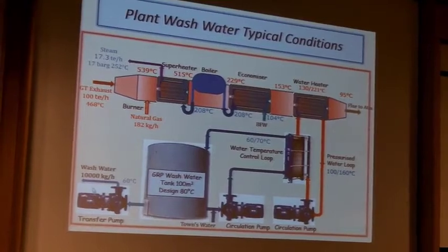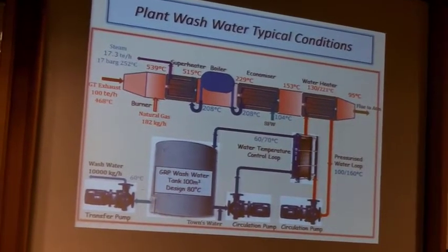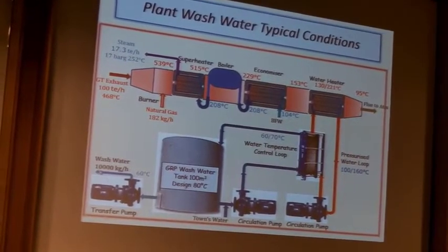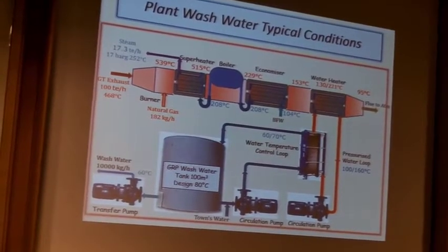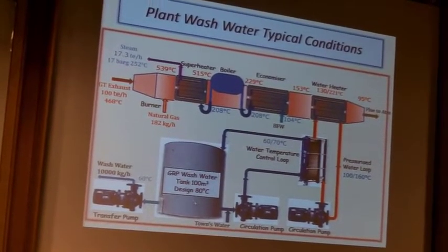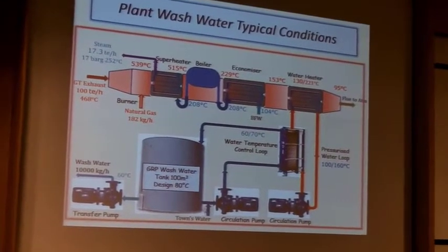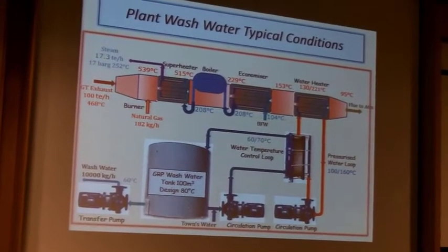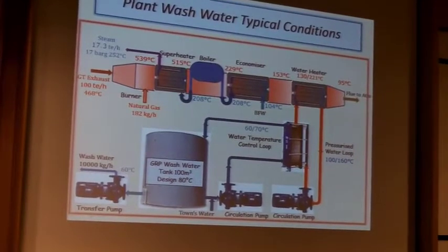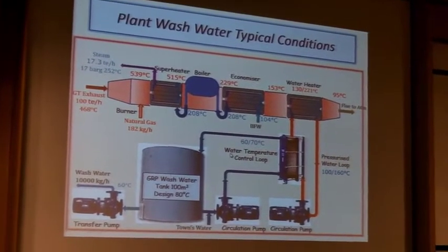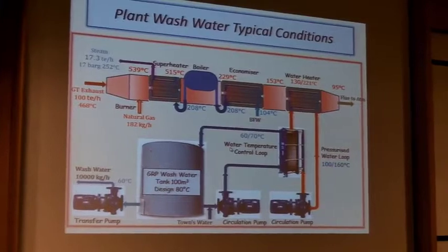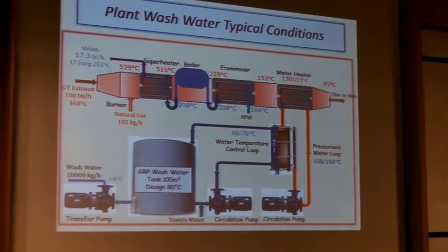And the maximum demand here was 10,000 kilograms an hour. So basically, as this came off, we were making up water in this tank with cold water from the town. So we're doing level control on the tank. So there was an interaction with the cold water coming into the tank and coming directly into the loop. So it was quite a little challenge, really.